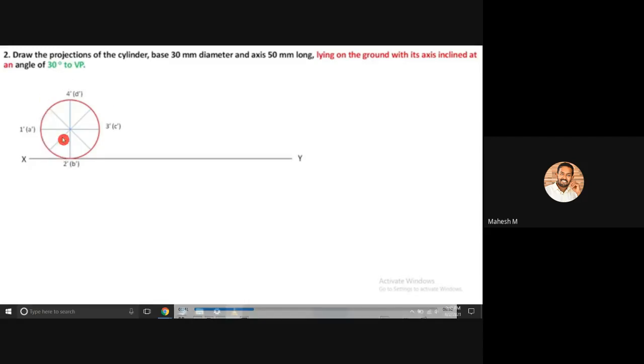But please try to provide all the points with the notation. Okay, so you have to mark the dimension for this, a diameter of 30 mm. Next, you have to project your front view towards the top view position. Please remember that a circle does not have a corner.